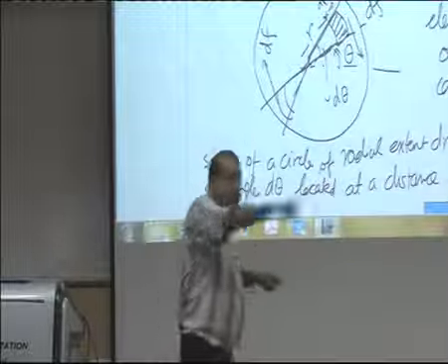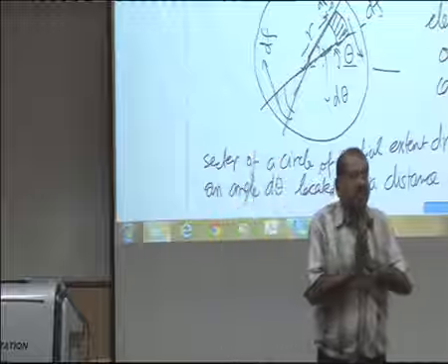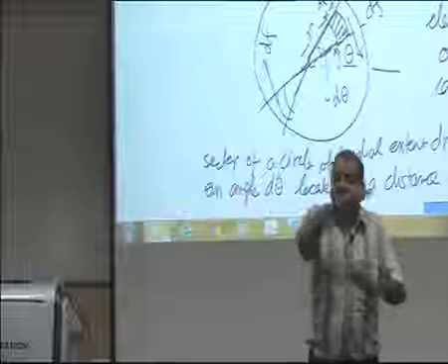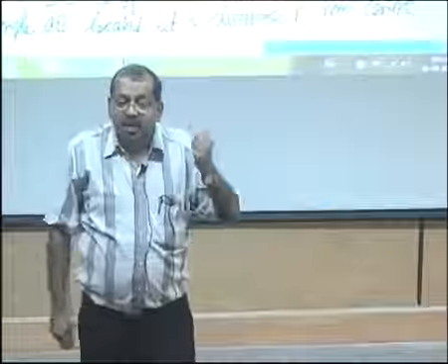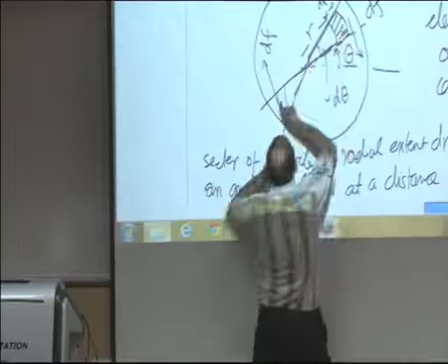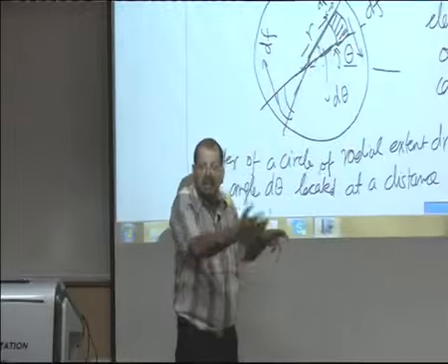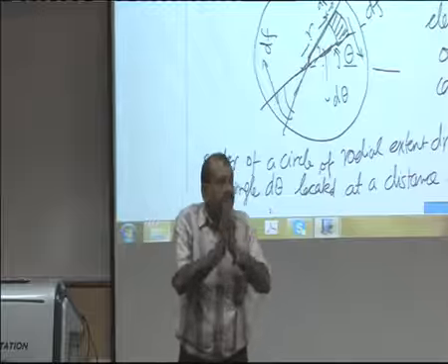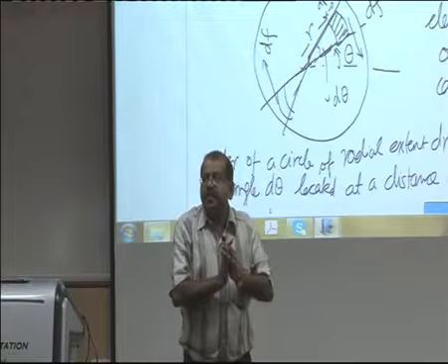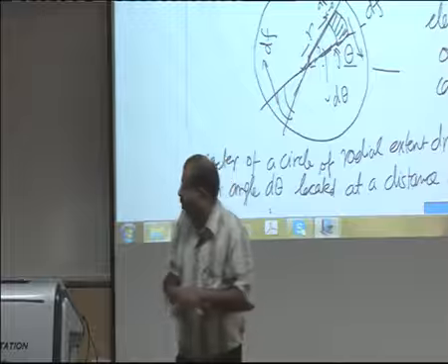Now, if I have to add up the total force due to friction, then it will be 0. But what friction is doing is, it is forming a couple, because about this point the moment is in the same direction. So, basically friction is not causing a force, it is forming a couple. Is that clear? So, that is what we do here.